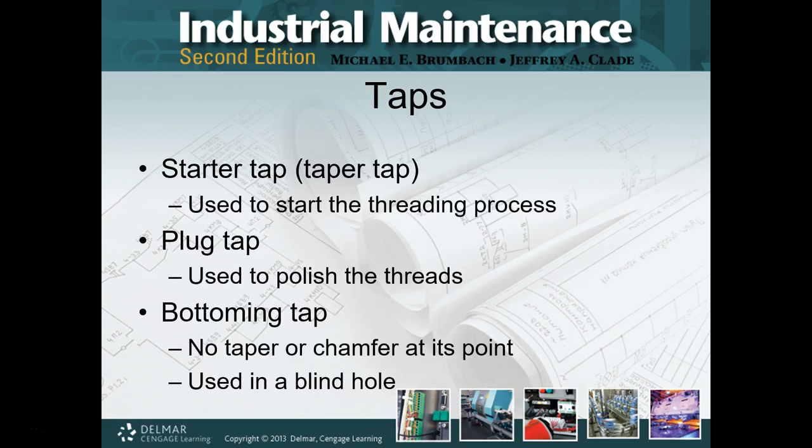And it's easier to use the proper handle, especially when you're doing taps, because here we go. We've got a starter tap or taper tap because we've got a really nice long taper on it. It's easy to get this tap into the hole, and so you can keep the tap a lot easier at a full 90 degrees, so it's perfectly in line with the hole as you start cutting the threads.